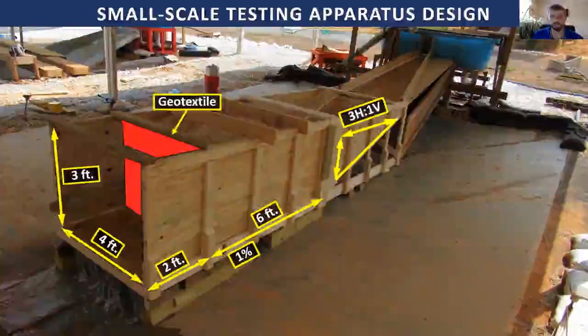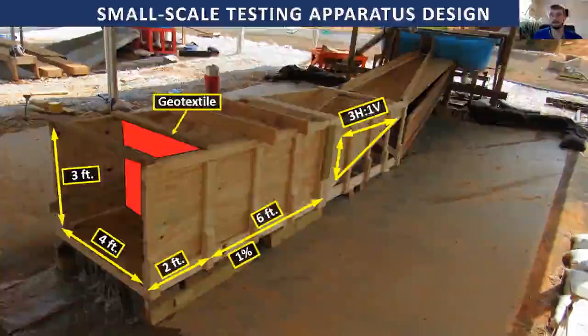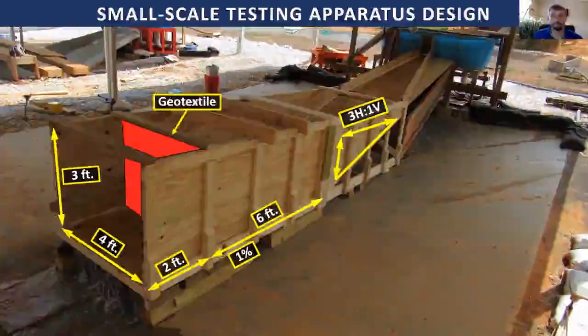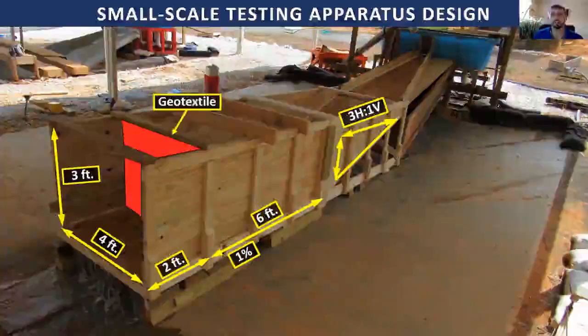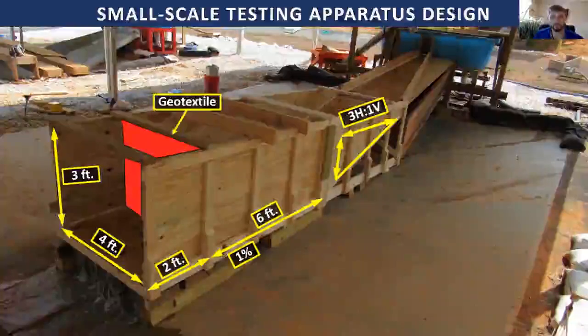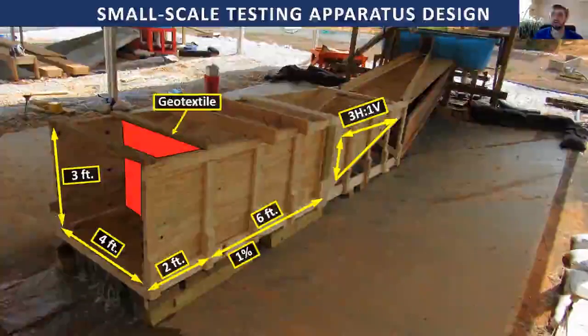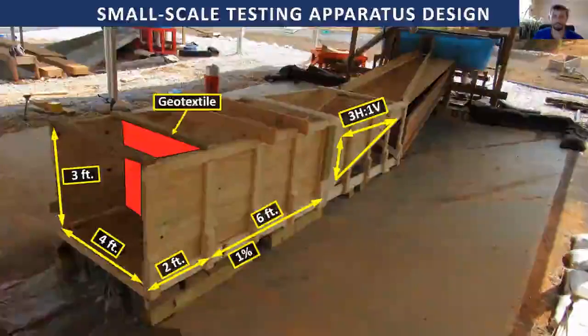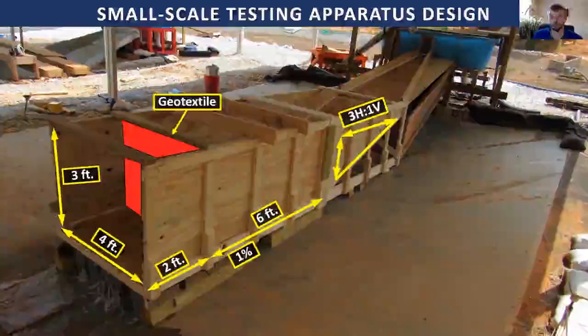And what's completely different about this particular testing process compared to the ASTM is that we actually introduce flow and sediment over a 30-minute duration, instead of just filling up a 20-gallon container, mixing it, and then releasing it to the geotextile. And we can adjust the flow that's being introduced as well as the amount of sediment based off calculations for geographical locations.